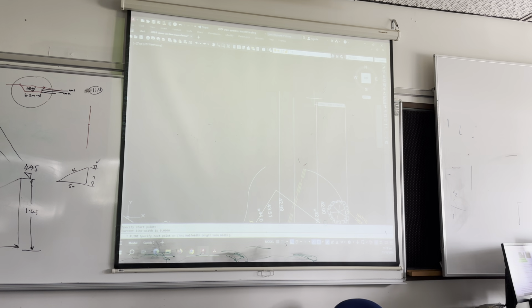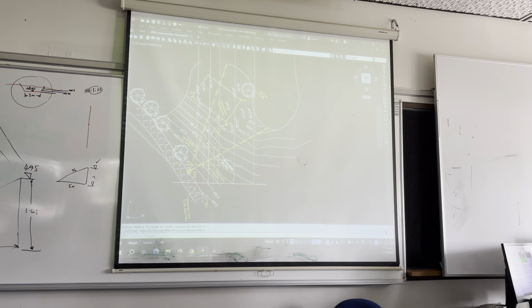Do a P line from here to there, to there, to there, and we can do a line out here somewhere, assuming, oh no, the path's level, isn't it? So we take a line up from the path. So extend the angle up to the path, and then do the path as level across there. So there's the cross-sectional area, basically going through that first cross-section, number 5 metres.